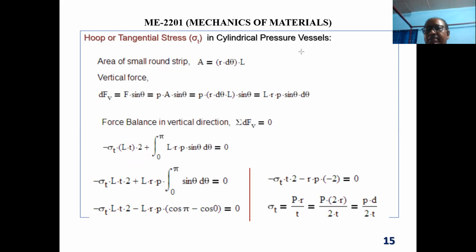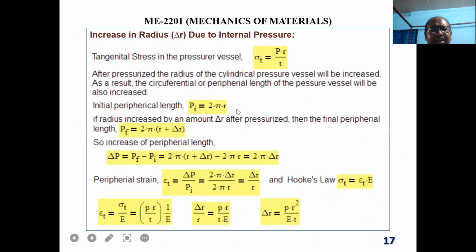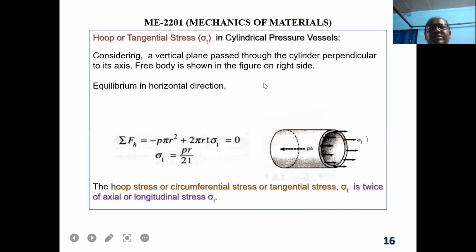And you have to derive it by using cylindrical coordinates. There is a lot of big derivation. Okay, thick wall pressure vessel. So this is tangential stress, and you have to derive one more stress. That one is called longitudinal stress. So longitudinal stress, actually, what happened? Due to the longitudinal stress, your pressure vessel just becomes two parts, right? Just cracks right over here.